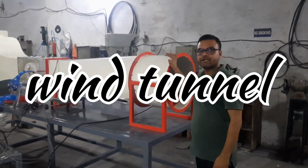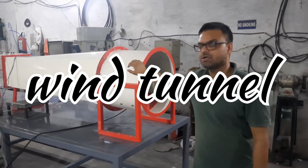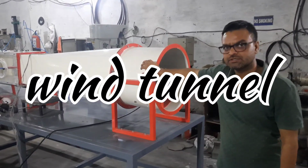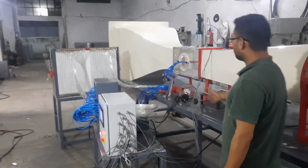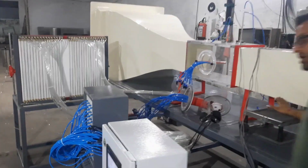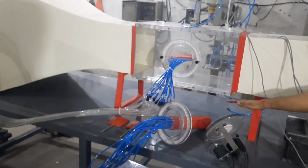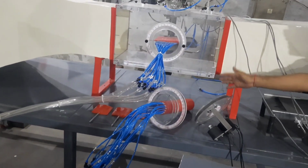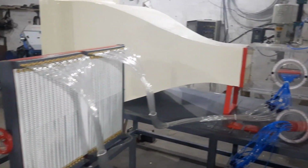This is a freestanding, compact, open circuit, suction type, subsonic wind tunnel used for studying various aerodynamic phenomena for undergraduate and research projects. The models provided with this apparatus can be used to investigate boundary layer analysis, drag and lift forces, pressure distribution around bodies, flow around bodies submerged in the flowing fluid, and also flow visualization around various bodies.